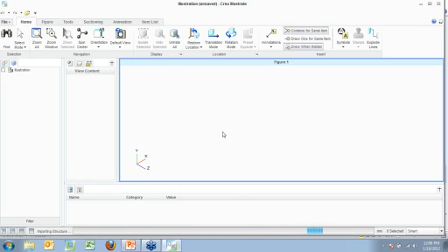So while this is importing, let me cover the import options again. You basically have three options. The first option is an embedded import. This just takes a snapshot of the CAD data. If you go in and change the CAD data after this point, nothing will update in your illustrations. Your second option is to choose linked and the always update option. This will update your illustrations automatically without asking your permission. And then the last option, which is the one I would use in most circumstances, is to choose linked and the update after confirmation only option.